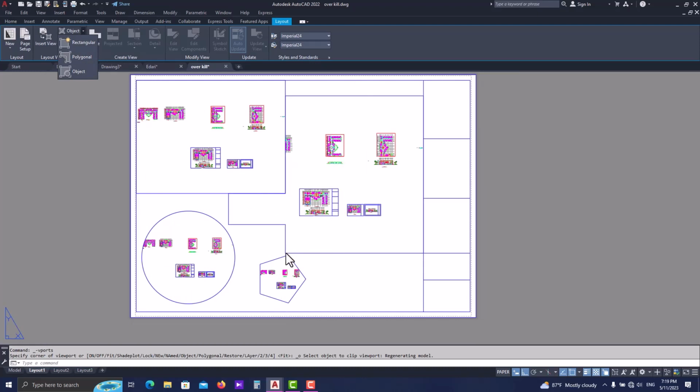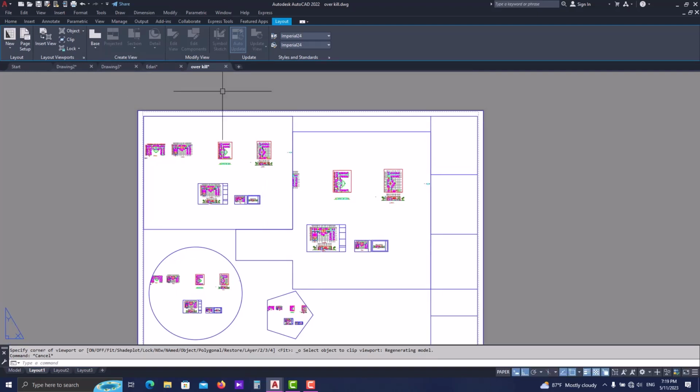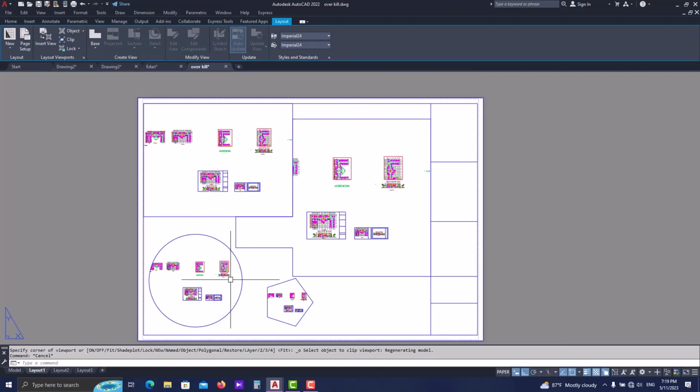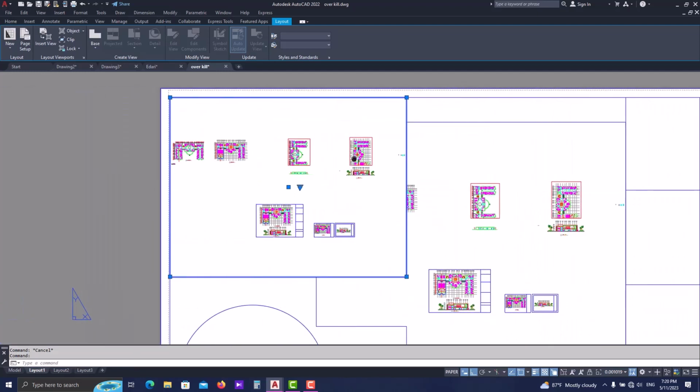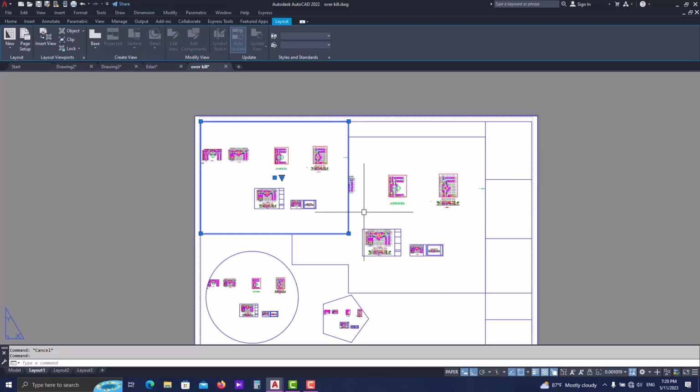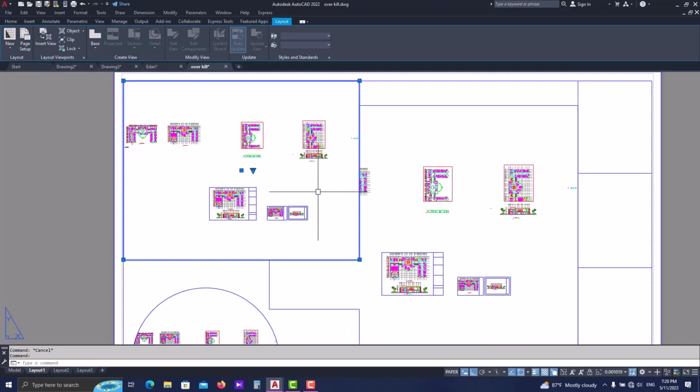Now, let's see how we can enter these separate boundaries, separate, you can say, viewports, and do some adjustments, modifications, for example, work on our sheets separately. All right. In order to do that, we can select one of these boundaries separately, and as soon as we do that, it would be activated. But if we use our mouse scroller, we can see that our whole paper would move. So we can get that we didn't enter the boundary completely.